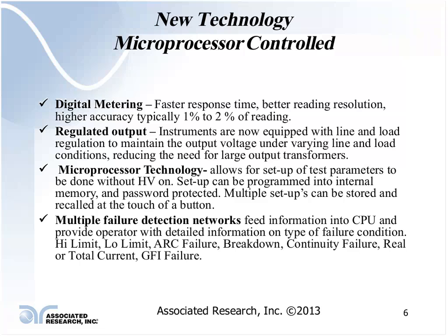If they are capable of maintaining the output voltage during the test through the use of feedback circuits, it does provide a higher degree of safety also for the operator. If you don't require such a brute force Hipot tester, it could create a much smaller shock hazard to the operator if they do make a mistake and somehow get shocked during the testing process.